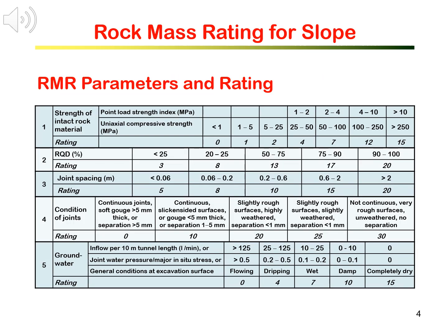We have learned how to compute the RMR, the rock mass rating, in rock mechanics principle class. Here, I reproduce the RMR table. RMR is assessed based on 5 rock mechanics parameters: the strength of intact rock material, the RQD, the joint spacing, the condition of joint, and the presence of groundwater.